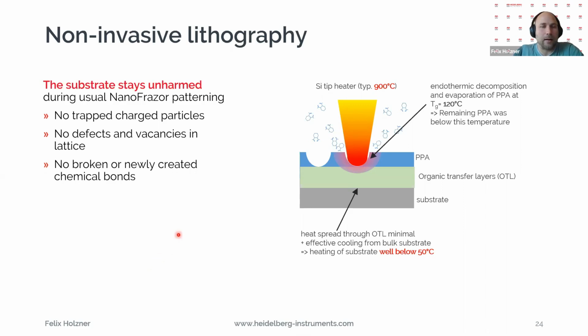It's also that in e-beam lithography, most of your energy is deposited actually in your substrate and can create, depending on your substrate, some damages, like vacancies, lattice defects, or you create new bonds between your resist, for example, and your top material. For many applications, that's not a problem, but there are some things where this is an issue. And we actually don't damage the substrate below. I mean, we have people who are afraid that with our hot tip, you would actually damage a sensitive material here. But also in a separate webinar, we will cover this whole topic of how hot it actually gets here, what's the temperature here, and what's the temperature here where your sensitive material might be. And you will see this is not heating up, maybe not even to 10 degrees or so. That's not heating up here. It's only heating up at the resist on top.